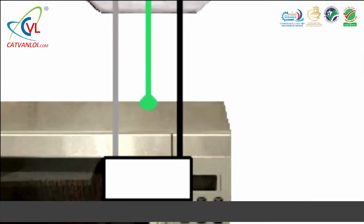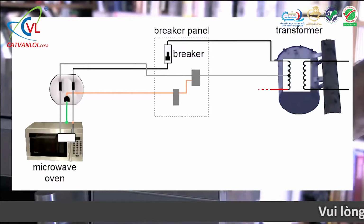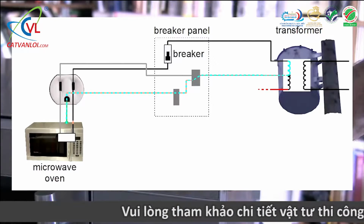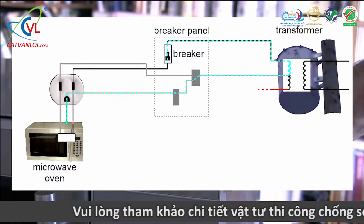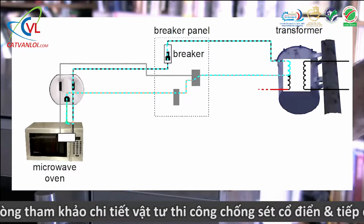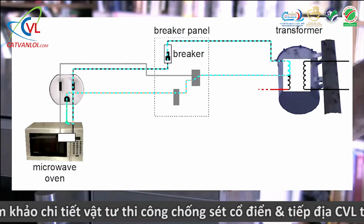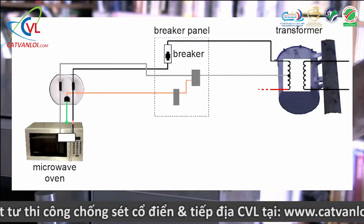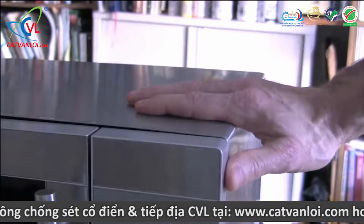Let's look at it again, but on the diagram. The problem starts when insulation on the hot wire breaks, and the wire touches the microwave oven's case. Since the case is connected to the ground wire, we now have this complete circuit, along the ground wire to the breaker panel, then along the neutral wire, onward to the transformer on the pole, through the transformer's coil, back through the hot, through the breaker, and continuing to the hot in the microwave oven, where it's touching the case. There's very little resistance along that circuit, and so the electrical current will be high enough to trip the breaker, which opens the circuit, making it safe to touch the microwave oven's case again.